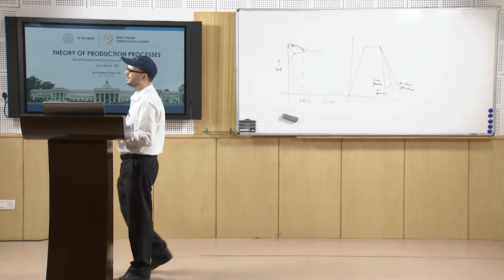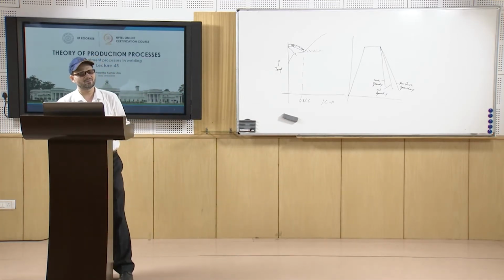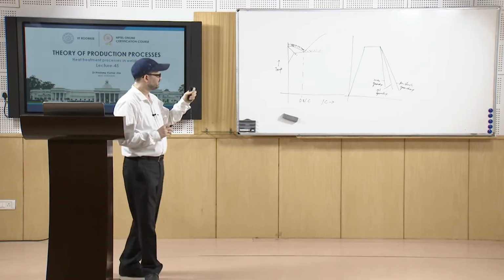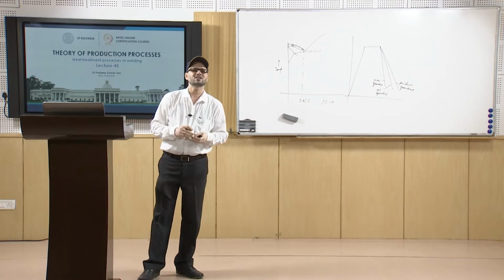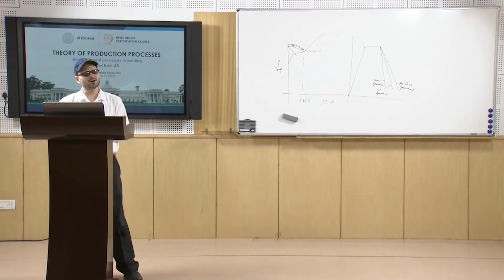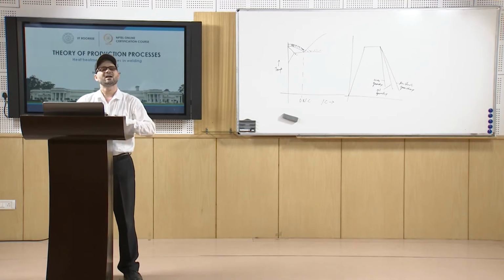If we get martensite in this situation, it is extremely brittle. So, that needs to be softened, and for that we do the tempering treatment,